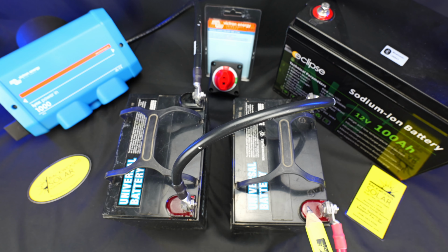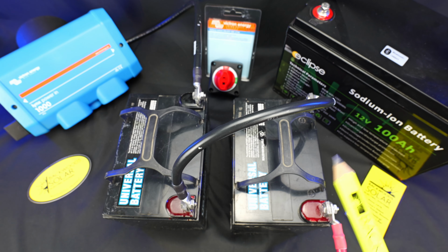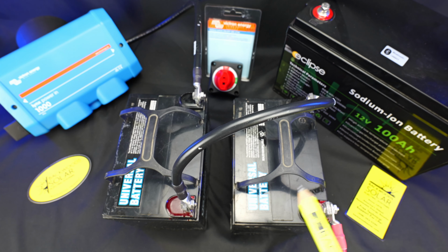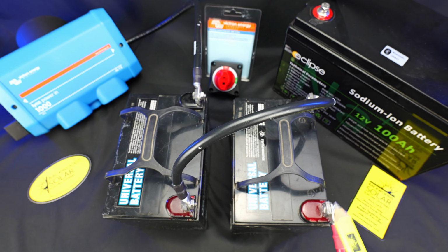I think it's best and just as effective to use really hot water to melt away any of that corrosion or crystal buildup. That way, in case any of that water gets into the battery, it's not going to cause any issues with the pH internally, like if we had a little bit of baking soda sneak inside that battery. So again, it's just as effective on dissolving that crystal buildup on the terminals, and I would just recommend using hot water to do that.